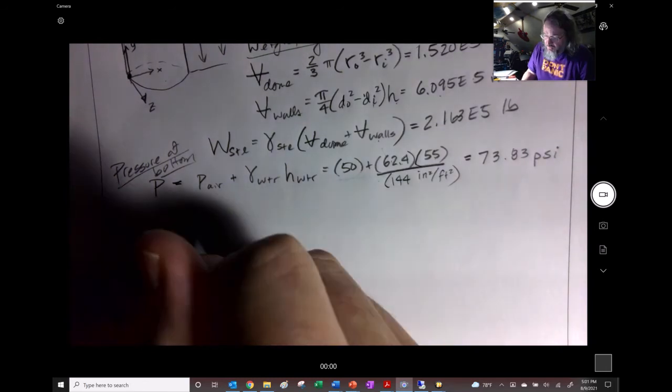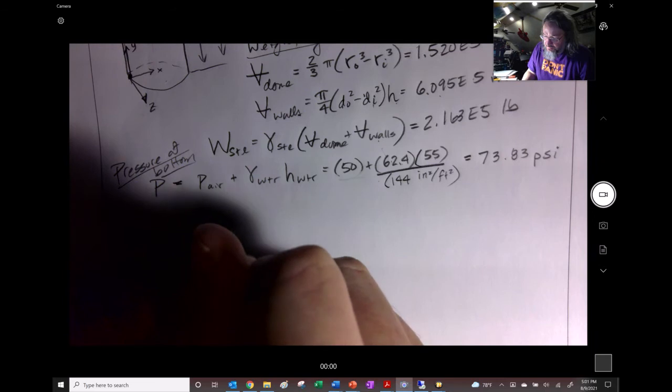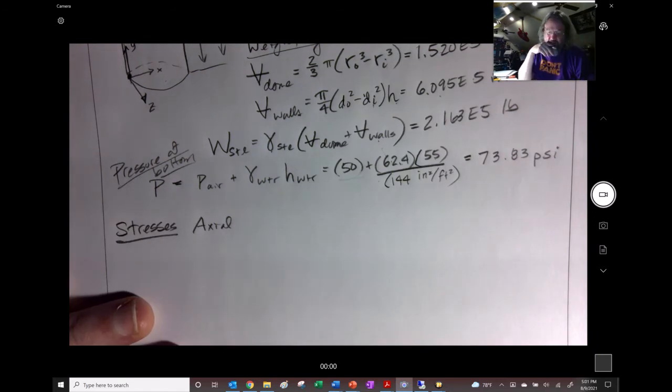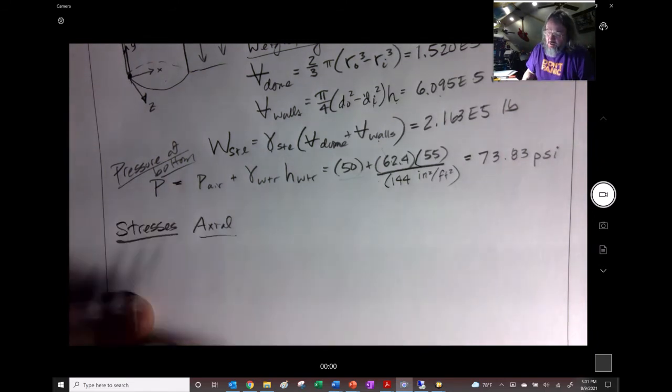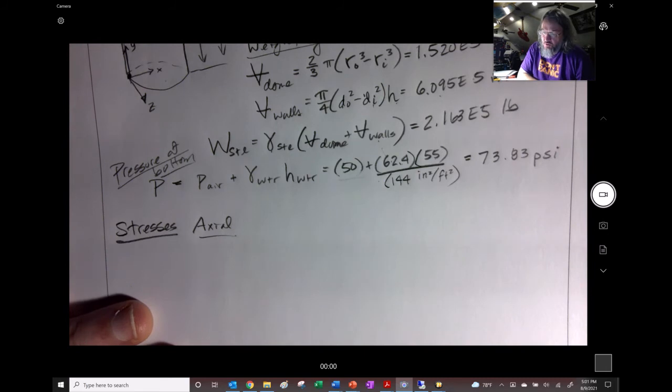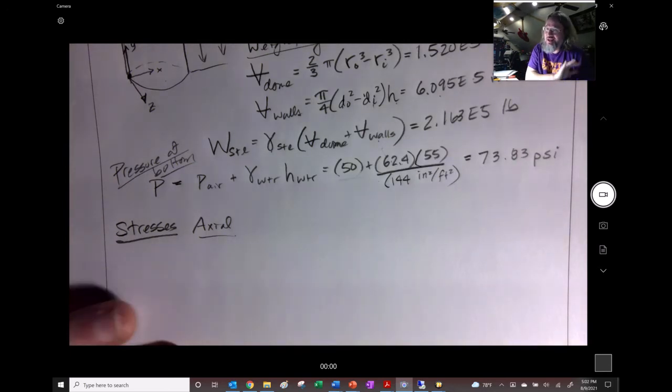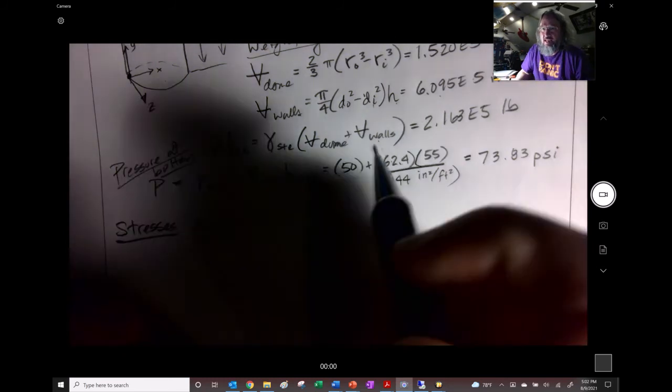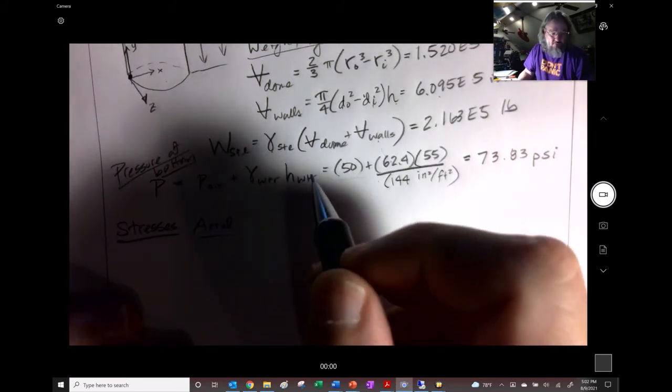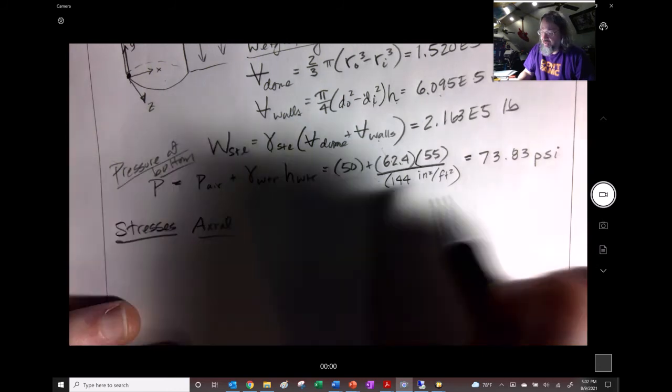So I'll write stresses, just to tell what I'm doing. And I'll start with axial. What kind of stress is axial on here? Well, there is some stuff that will align with the axis, but let's just keep them designated by what we would generally call them, right? For instance, longitudinal stress is in the same direction, but it has its own category, so let's leave it alone. The only axial stress is really going to be from the compression of the weight, right?